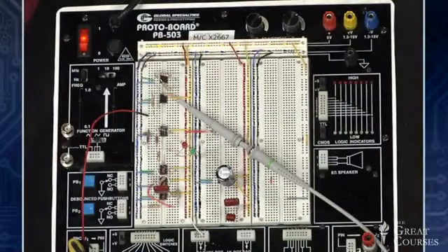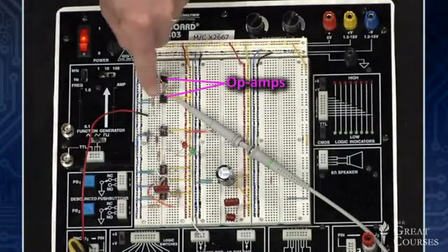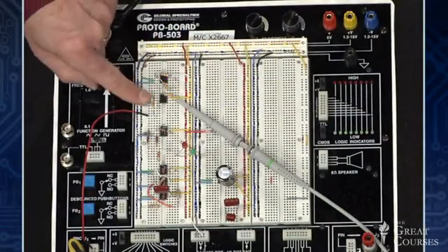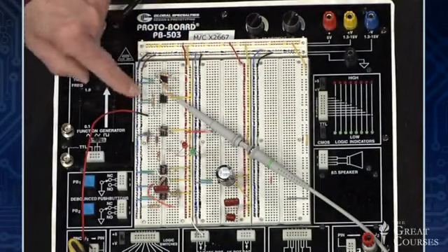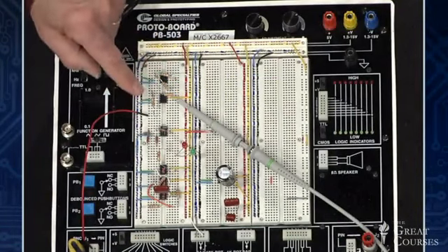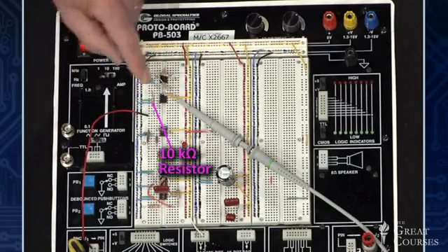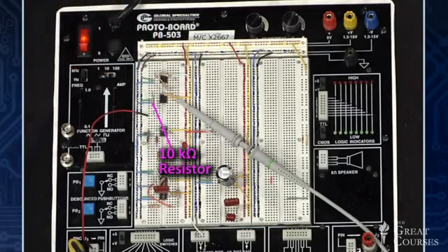Well, let's take a look at the real thing instead of just looking at things we can do in simulation or by drawing circuit diagrams. And what you see is a couple of op-amps. There's the first one. That's the very same op-amp we used in the previous lecture. I've just changed the resistors a little bit. I've got a 10 kilo ohm resistor at the input, and the closest I could get in the standard resistor values was a 33 kilo ohm, so this is more like a gain of 3.3.